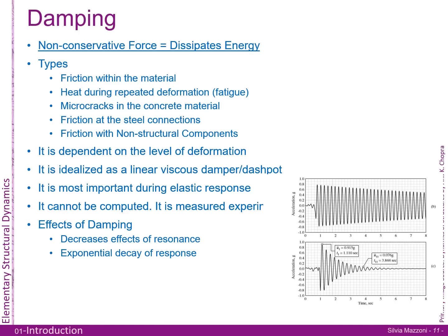And what are the effects? It decreases the effects of resonance, so that's a really good thing, and we're going to talk about that. Resonance is when a system is excited at its natural frequency, so it would actually excite a long time. And there's a video at some point I will show you about a bridge that actually collapsed because the wind came in and hit the resonant frequency. And so nowadays you just need to add some dampers to these systems so that you're messing with the natural frequency of your system and you won't have collapse due to resonance.